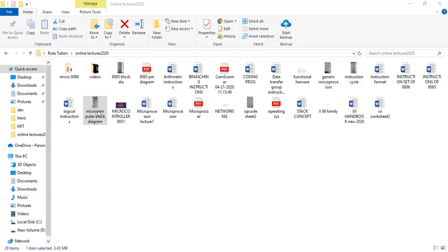So keyboard and display are your input and output devices. Keyboard interface and display interface are the interfacing ICs. Why are they required? Because the input output devices are slower than your CPU. In order to match their speed with the CPU, we use a keyboard interface for the keyboard and a display interface for the display. The MPU or CPU is the central processing unit, which controls the whole action and processes the data. It requires a clock signal that is given by the clock.